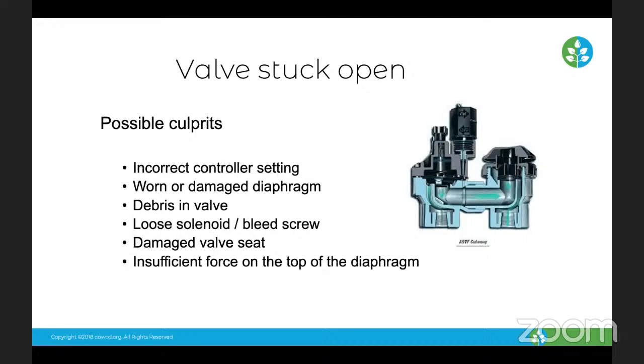A worn or damaged diaphragm. Going back to that video, when you remove the bonnet, that's the rubber component that moves up and down. So that's this section here. Over time, it's moving up and down, especially if you live in an area that has hard water. The diaphragm will wear and could break.